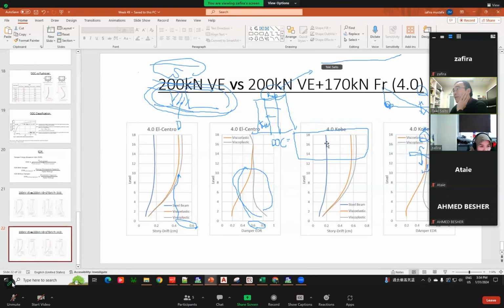Okay, so for example, in case of 1/1000, you can use the elastic KB, but at 1/200, 1/100 or 1/50, if the beam is getting damaged, you reduce this KB to an equivalent stiffness. Okay.